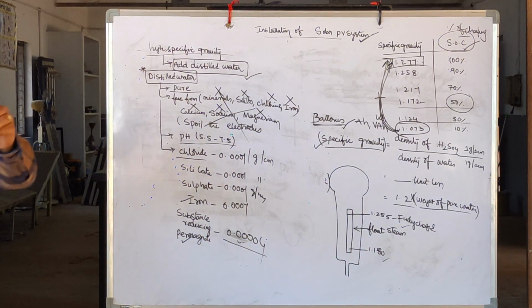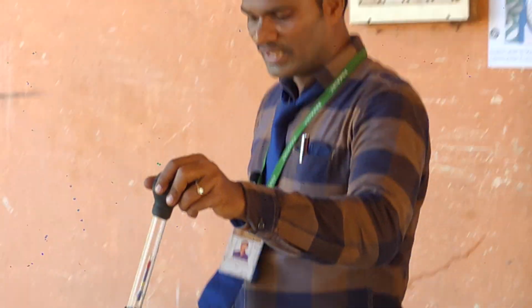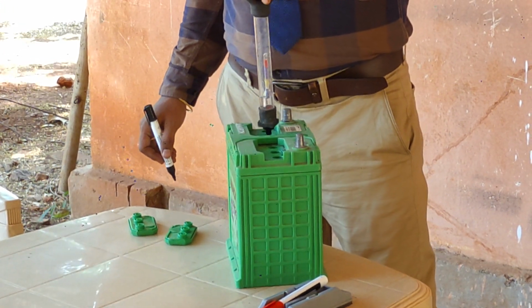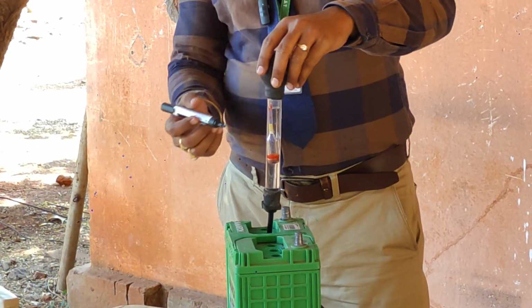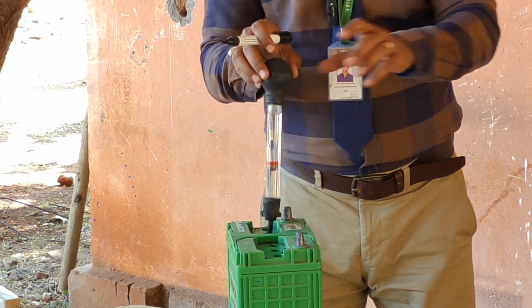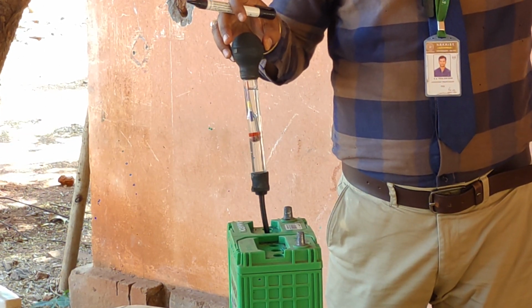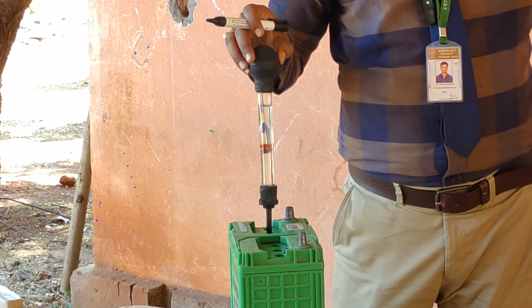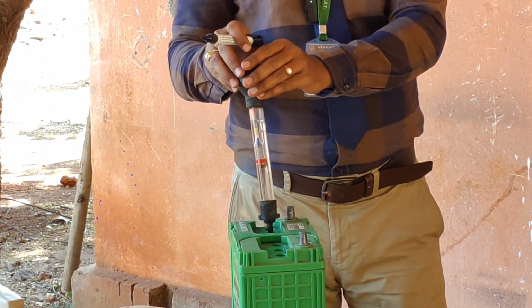The meter used to measure the specific gravity is nothing but a hydrometer. Very simple. It has a nozzle. Just insert it into the cell and apply some pressure. Automatically water will be sucked inside. Again, what is the color it is showing? Red color. And what is that value? 1.0. 1.0 means where does it come? 10%. So what do I have to do with this cell? I have to top up with which water? Distilled water, and then I have to keep the charging. Now what is the amount of charge available? Only 10%. After topping up with distilled water and keeping it on charging, how much percentage will it get? 100%.